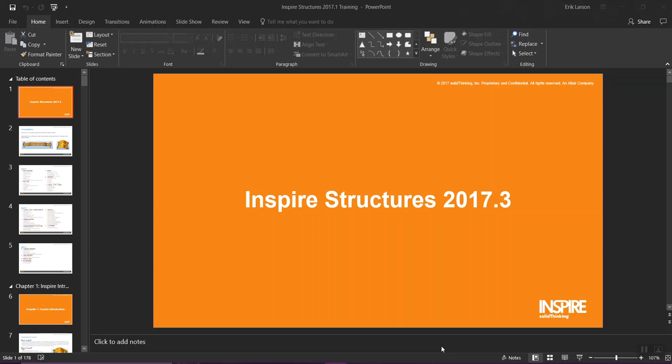And what we do is we take a structure, complex or even simple, and we discretize it. We break it down into little elements, little pieces. Because while we can't solve for the entire structure, we can solve for each one of the little pieces. And we treat each one of those little pieces as if it were a spring.